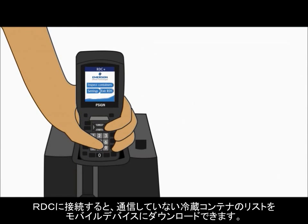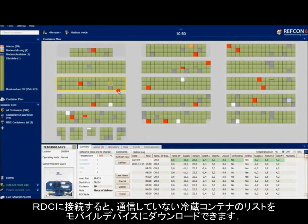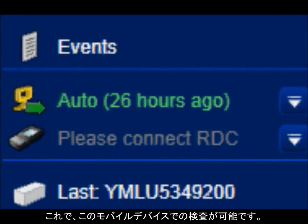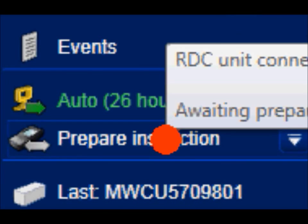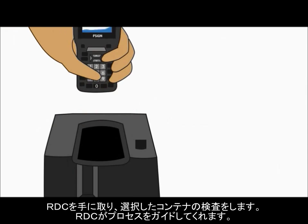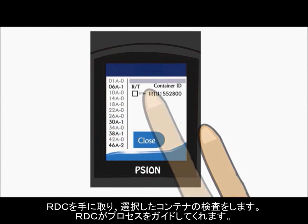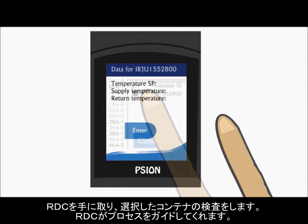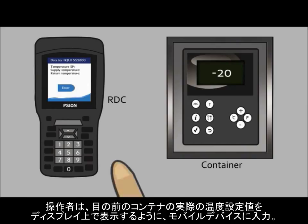When you connect the RDC, you can download a list of non-communicating reefers to the handheld. Hereafter, you can make your inspection with the handheld. Pick up the RDC and inspect the selected containers. The RDC will guide you through the process. Enter on the handheld what the display on the container in front of you tells you that the actual temperature set point is.